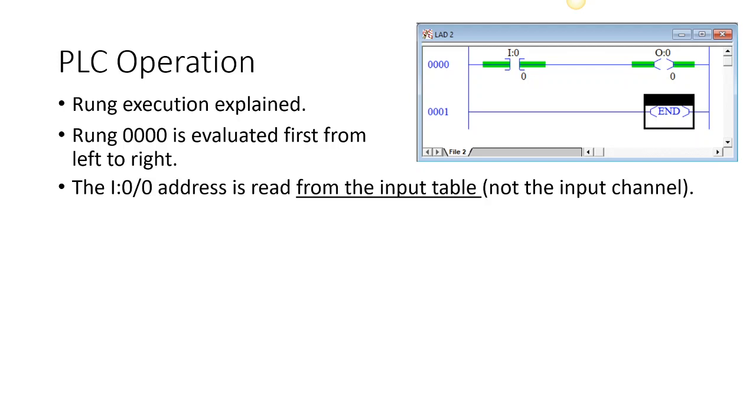It's going to pass the test. And when it passes the test, inside a running program, it will highlight itself green. Now that doesn't mean that it's, quote, energized like electrically. What it means is it's logically true. And when it is logically true, you can think of logical continuity as electricity. Logically, it's passing on that true down the line.